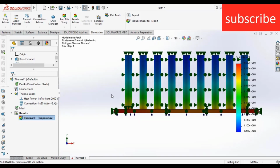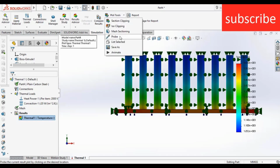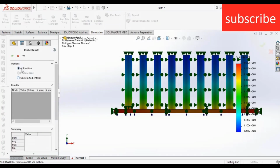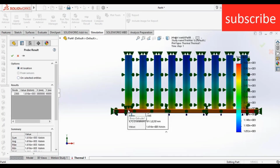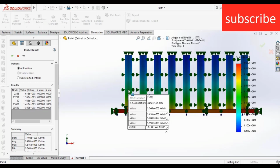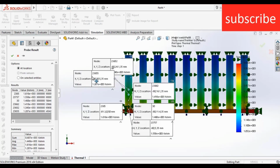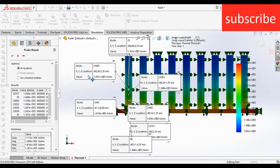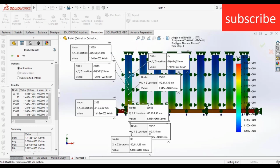Now a question arises in your mind, how can I see the temperature curve? There are two ways. The first way is go to Probe tools, click on Probe. After that, make sure you select add location. Now select the bottom. After that, select the top plate. Now in a similar way, just select a point at the top so that you will get a graph.